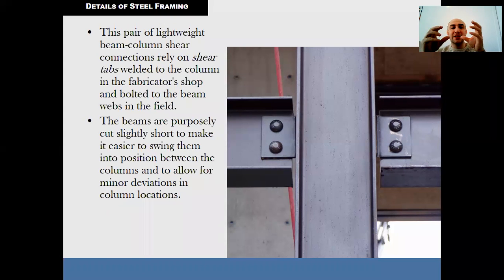Shear connections do not resist much moment force, as they allow some looseness to rotate, which is one of the main differences between the shear and the moment connection. It is worth noting that a welded connection resists higher moment loads than a bolted one.